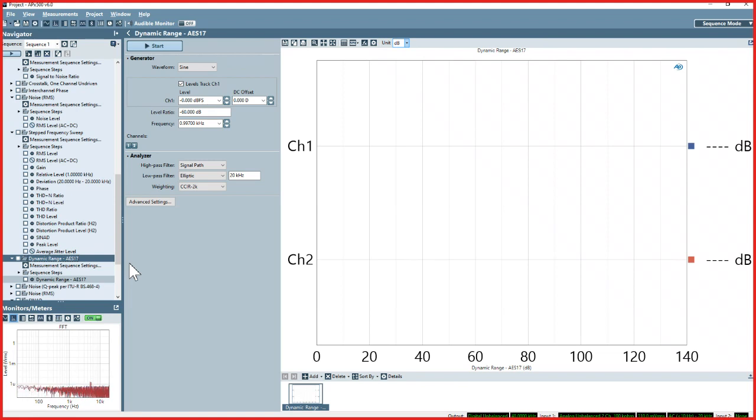But in this measurement, again, we drive the device with a full scale signal, but then instead of turning the signal generator off entirely, we turn the signal generator down by 60 dBFS, and we then remove that minus 60 dBFS signal from the output with a notch filter.